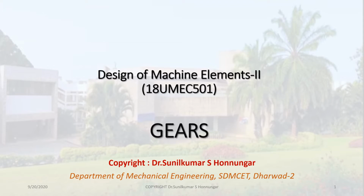Basically, we have three types of design modules in gear: one is static load design, then dynamic load, and then wear load. Static we have seen, in which there are 5 different sub-steps of design, like assuming the material, then the minimum number of teeth on the pinion, then finding the module, and then checking for induced stress and the percentage variation. I think by this time you have already gone through that video.